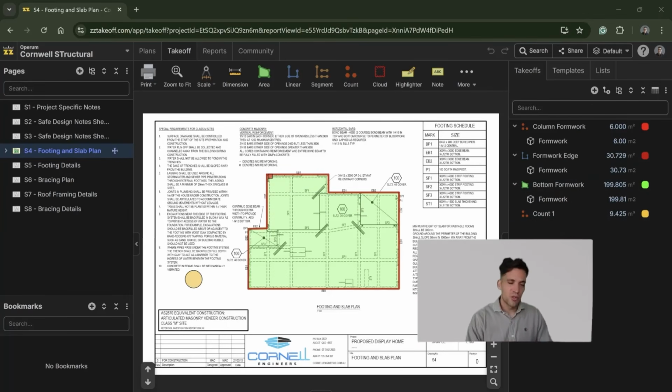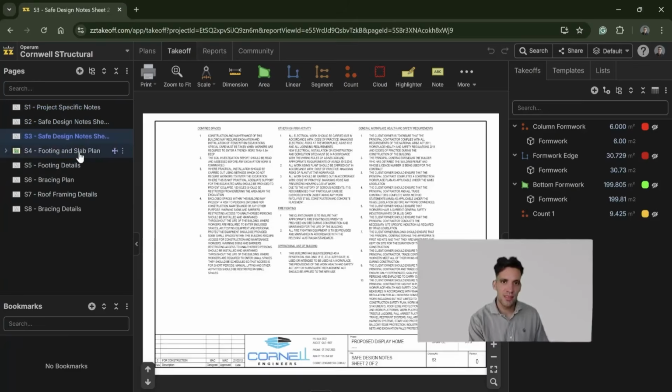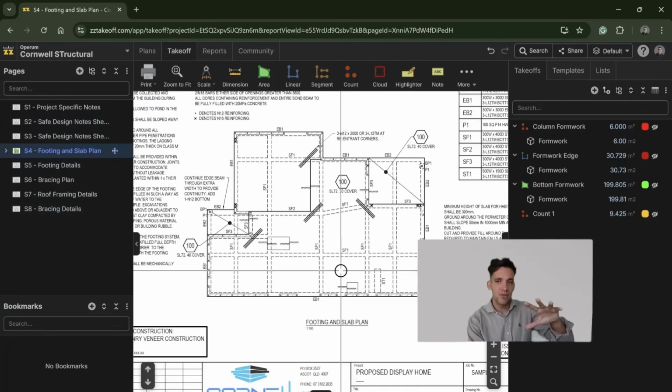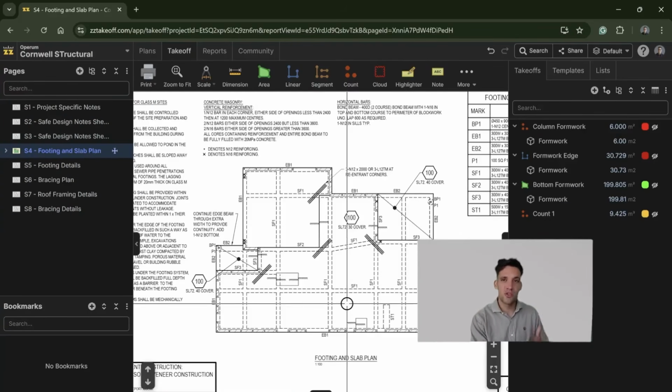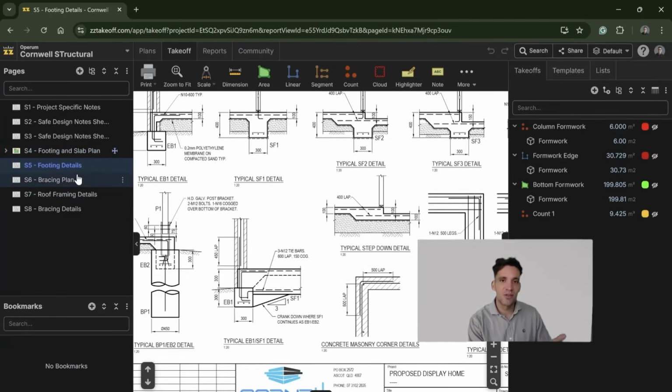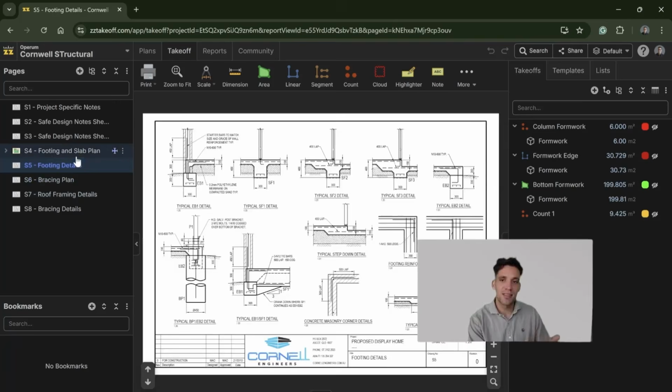So when we're doing a structural quantity takeoff, there's 3 things we're measuring. We're measuring the volume of concrete, we're measuring the meters squared, or if you're using imperial, the square feet of formwork, and the mass of steel reinforcement in kilograms or tons. When you first open a set of construction drawings, there's generally 2 types of drawings you're looking at. You're looking at the plan views, which give you an overview, which is the drawing you're going to do all your takeoffs on. And then you'll have a series of section views that supplement and support this.